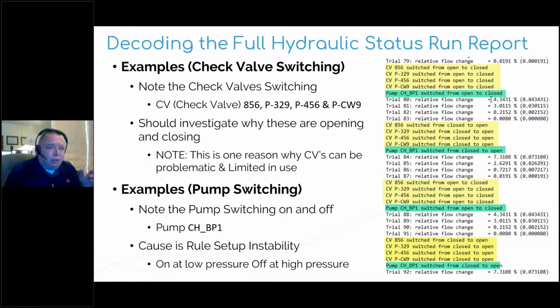The simple controls, as you can see, are evaluated as it's converging. Rule-based controls, it waits until the model converges to a solution, then it evaluates them, but it doesn't implement them until the current time plus the rule time shift. So there's a delay.